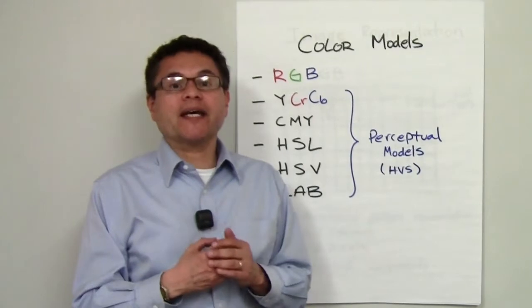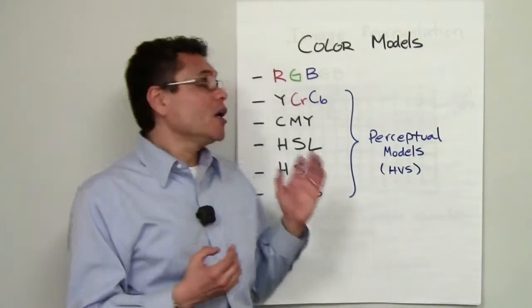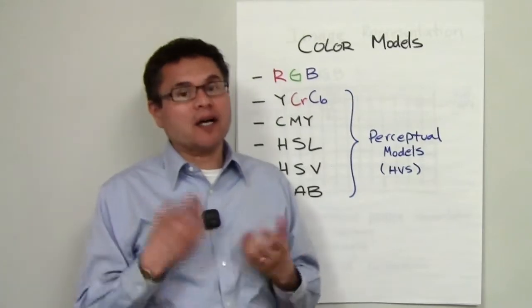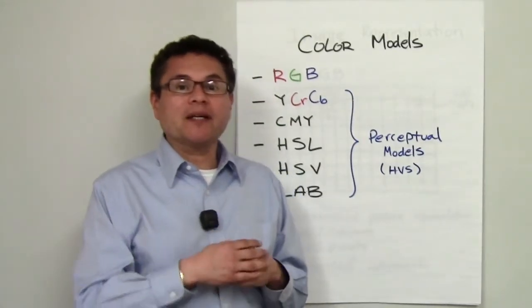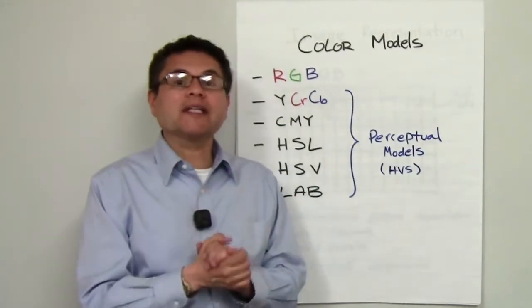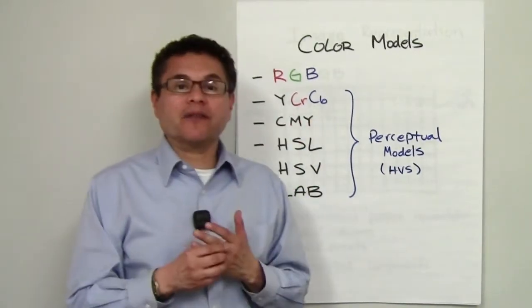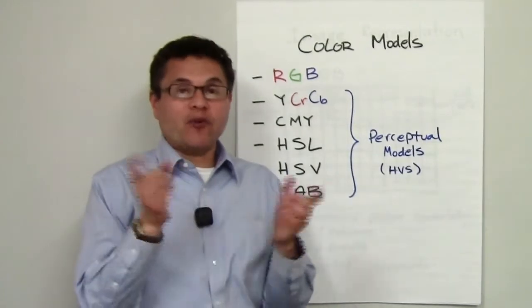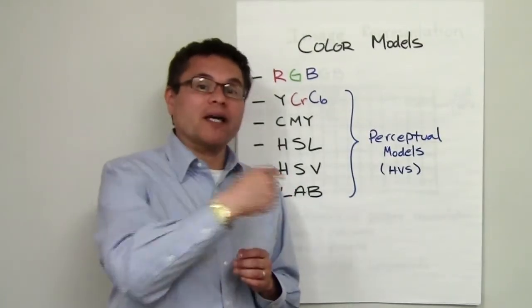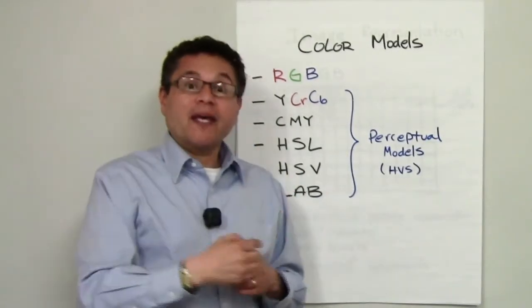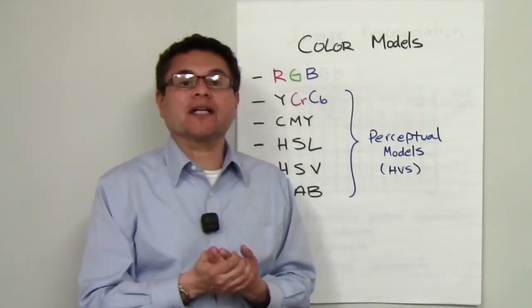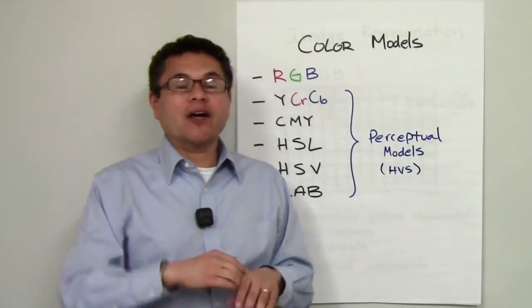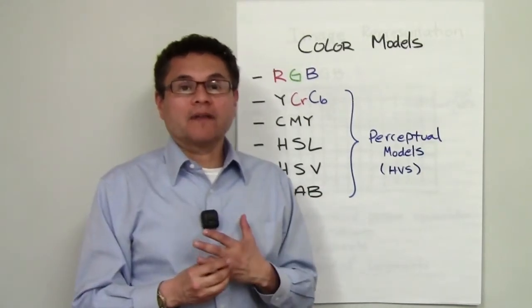In this case, it is a color difference signal when you talk about YCrCb. CrCb being a color difference in the red, meaning color difference from the luminance, and the blue, a color difference for blue from the luminance. In a formula, it would be R minus Y and B minus Y. And so it's a color difference signal that allows you to represent with 3 color primaries the whole spectrum of images.